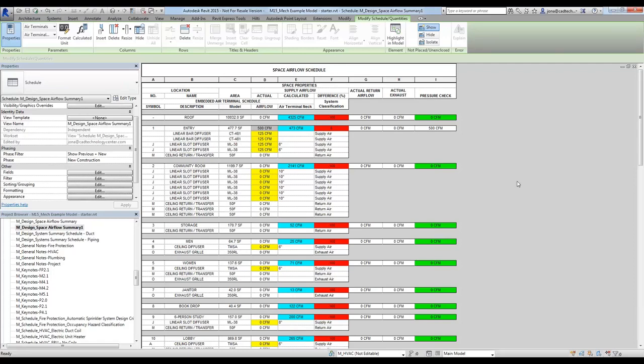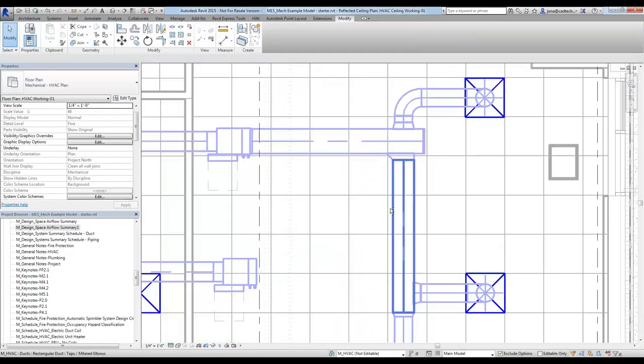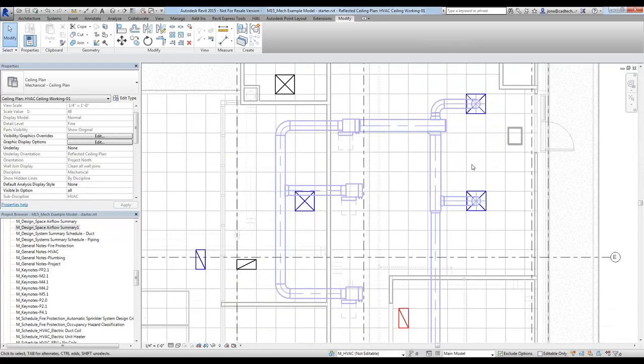I have a room schedule. I have an idea of the systems that I'm going to be putting in. Is it constant volume? Is it variable air? What are we doing? And I will basically work off of this schedule from the very beginning. And then once we start finalizing layout, if we finally get a ceiling grid, then I can start aligning to ceiling grids.